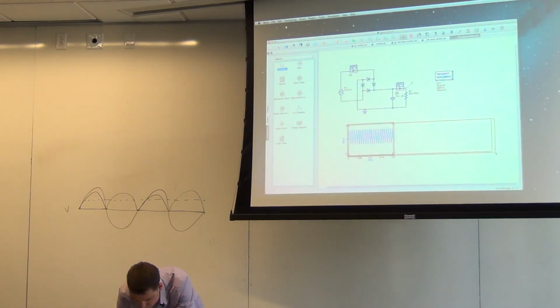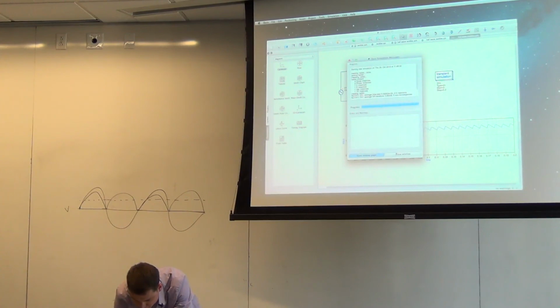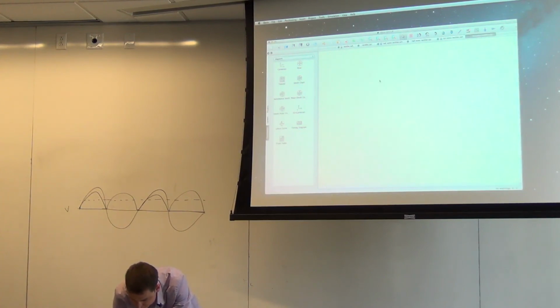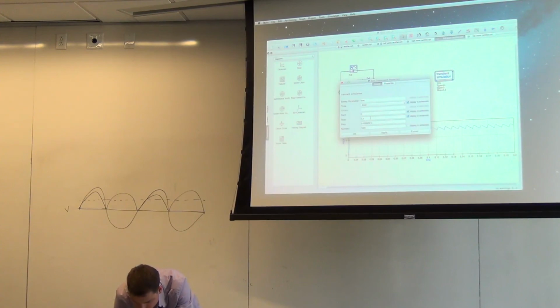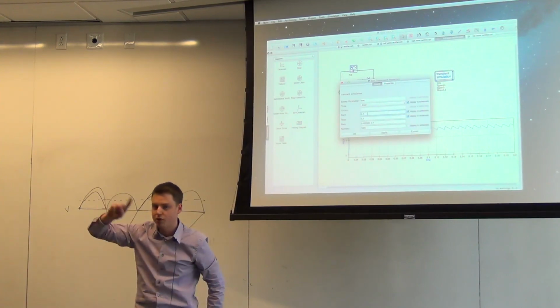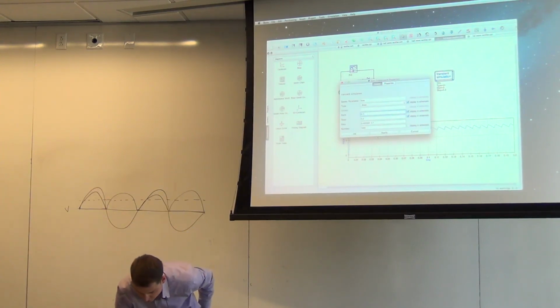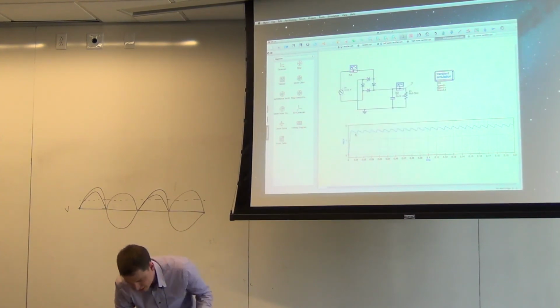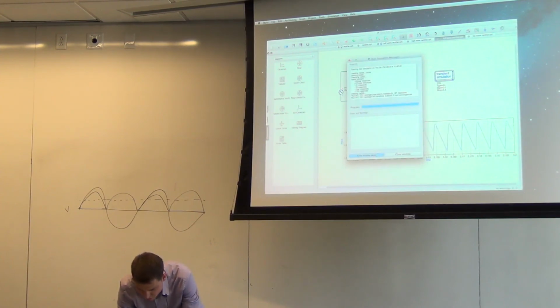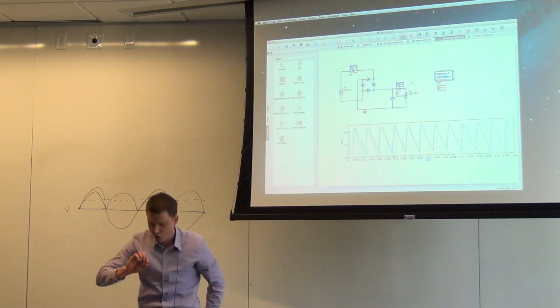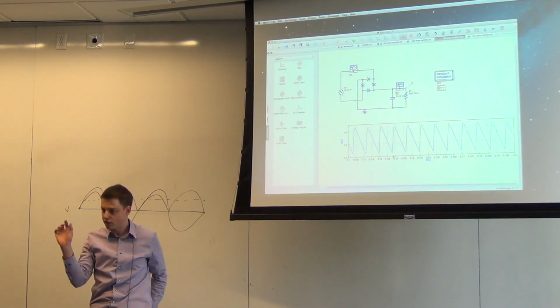It looks reasonable, right? So it's sort of DC. Let me make that a little bit bigger, actually. And you know what? This time, let me change the transient simulation this way. So that looks a little better. Let me change this so that we don't start at 0, so we don't look at the time when it builds up charge. Let's just look at the time when it's settled to its steady state. I mean, steady state in a different sense than AC steady state. Okay. So that's what the current through the element itself looks like. So this is a DC signal.